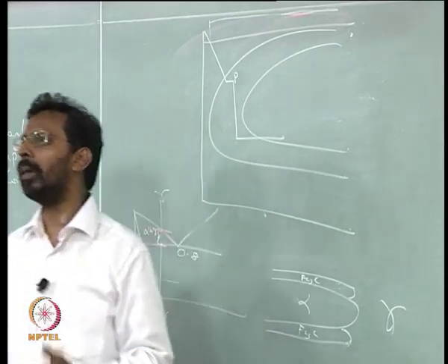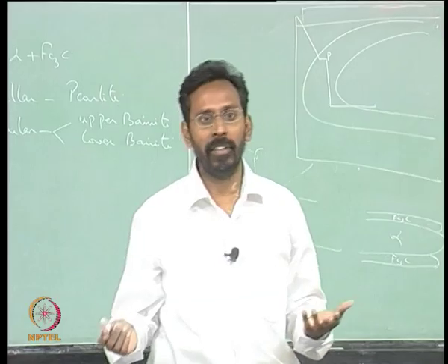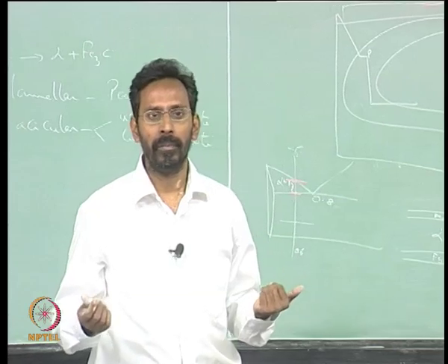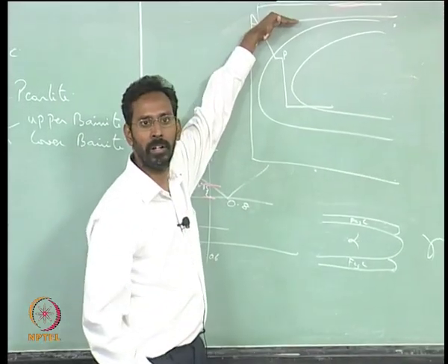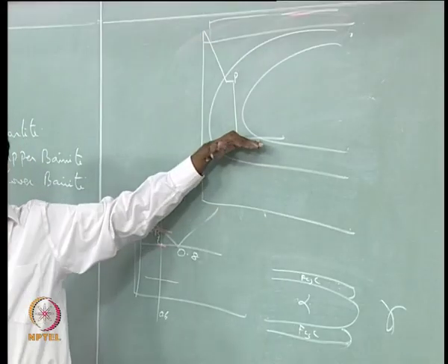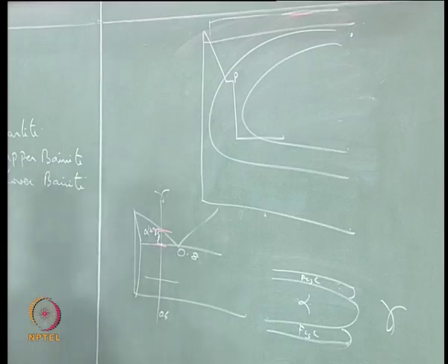It may grow, but at a very slow rate, but at the same time the gamma that is there is not stable at that temperature, because you are far away from the A1 temperature. So this gamma has to somehow transform, so as a result new nucleation events will occur.